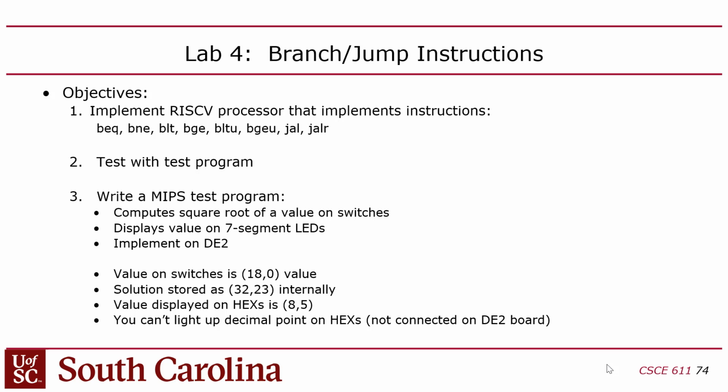Now it'll have a little error because of the format we're going to use. What format did you guys use for lab 1? It was 14 fractional bits, right? So 14 fractional bits has an accuracy of 2 to the negative 14th power, which is 1 over 16,000, right? But on the board, the smallest number is 1/100,000th. So 1 over 16,000 is a bigger number than 1 over 100,000, which means that the hex displays have more precision than your code's going to have.